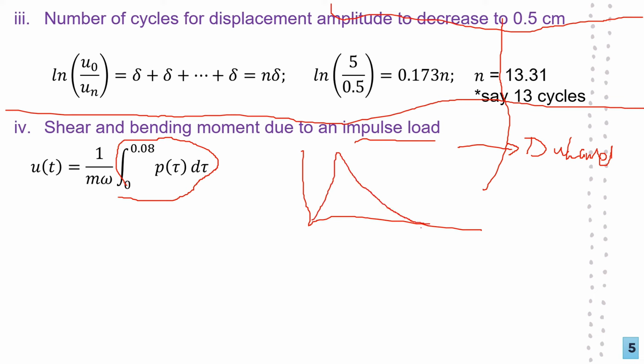You may find, like this is the t, our motion will continue after the impact. You know, when you hit the structure, the motion will continue, maybe as free vibration. So the time will continue. There's a time, this is the time we are calling tau, between 0, when just for a very small time the impact or the impulse is acting, 0 to tau, that's the integration of that part. So this is the dynamic response. This is the response just when this force is acting.